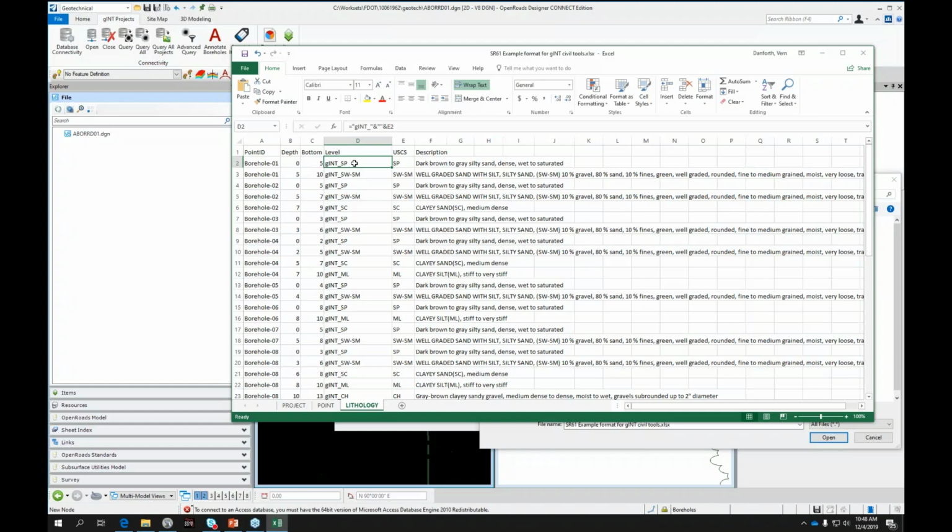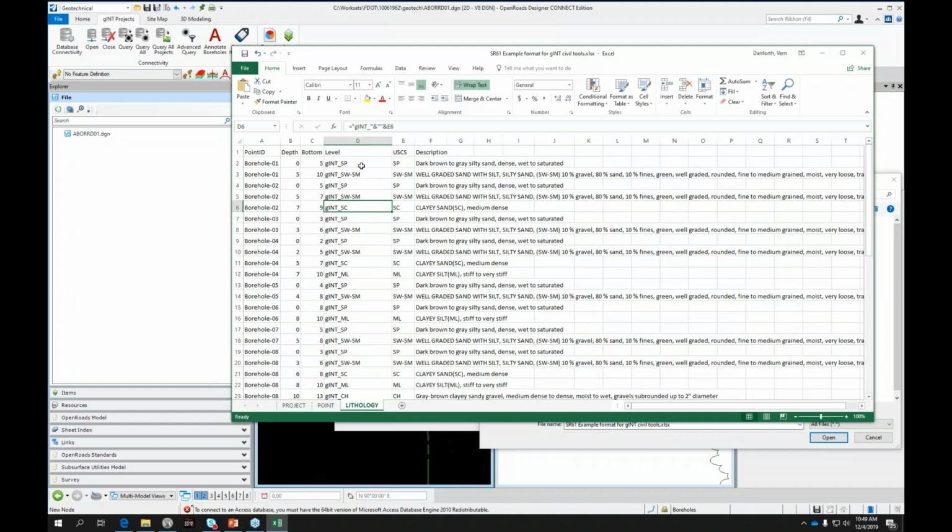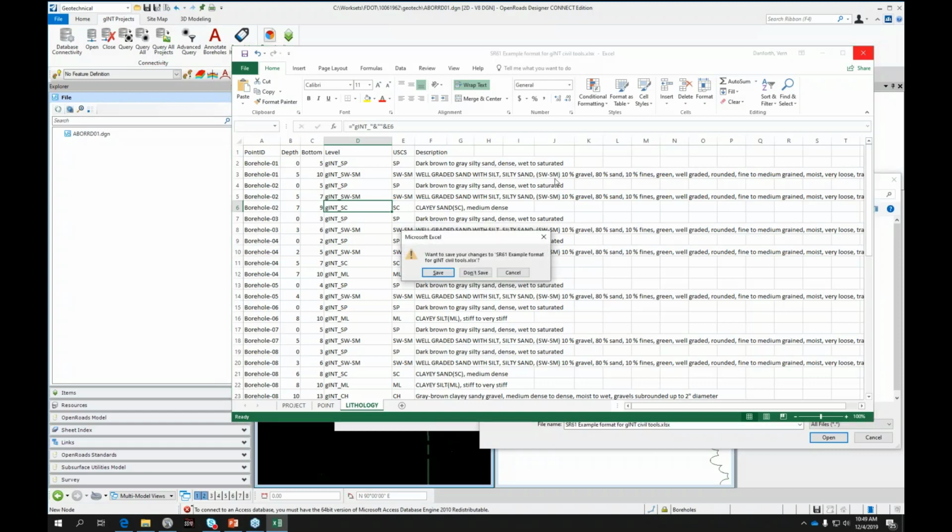And this is where, if this comes blank from your geotech, you can actually go in here and match up the level to the level that you want it to plot on. Or you could ask the geotech engineer to actually use the FDOT levels, and they'll be in the CAD manual as far as which levels to use. Like I said, right now we just have the USCS levels. I'll probably be adding the AASHTO levels as well if they want to classify by that classification type. And then once you have all those, it's just a matter of connecting to it.